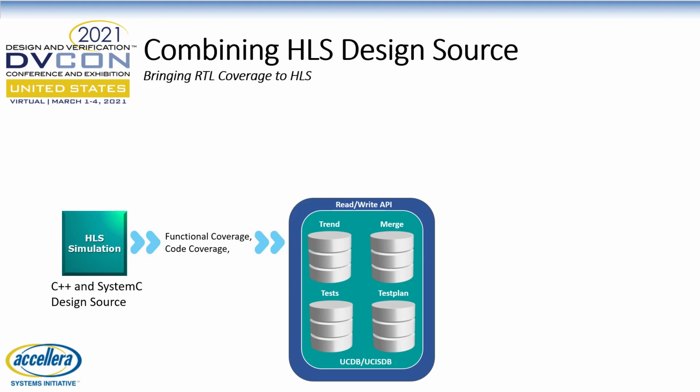One of the primary motivations to use Catapult coverage rather than, say, gcov or lcov is that Catapult coverage is HLS synthesis aware. This means that unlike gcov and other software-centric code coverage tools, Catapult coverage is aware that inline functions will be unique instances in post-HLS RTL, and thus reports coverage on a per-instance basis.